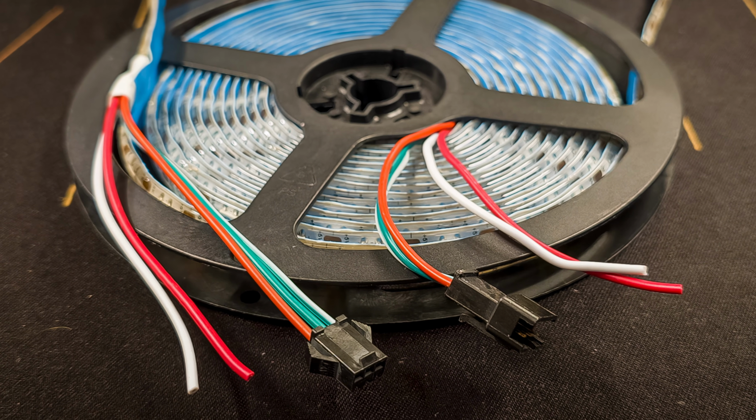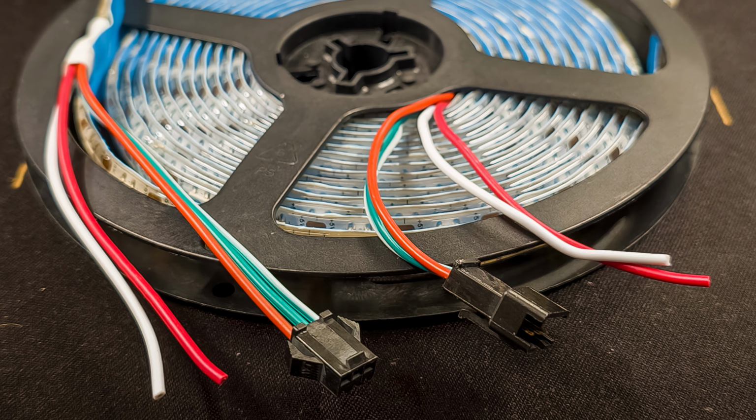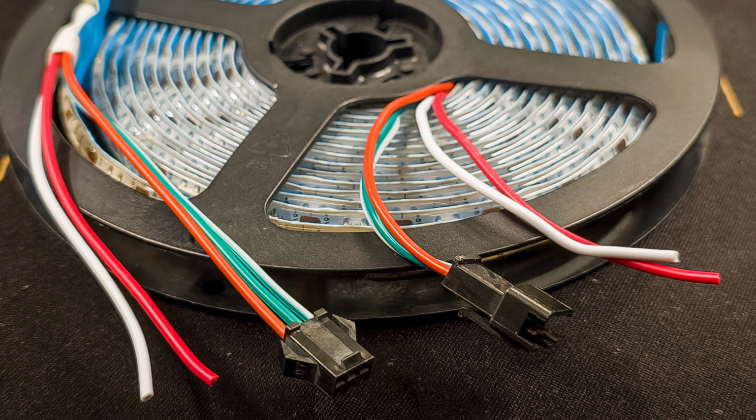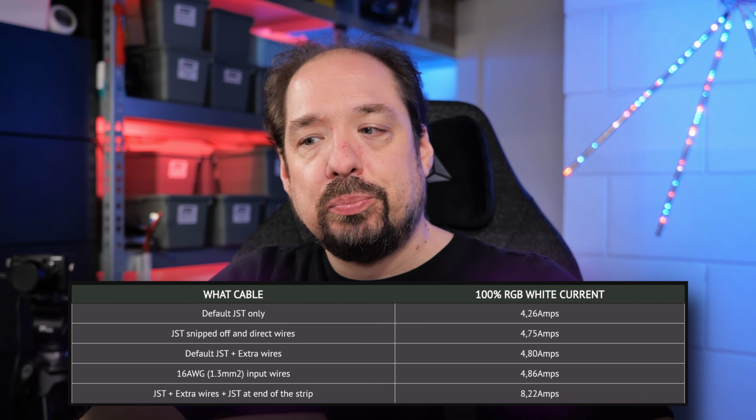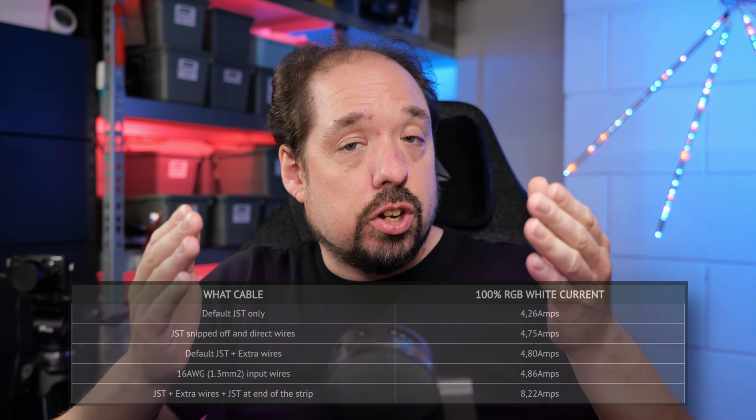Just to make it easier, you can inject at any point, but then you have to solder. And generally these strips come with those little two pigtail wires attached. At the front of this video, we already tested that, and we can use those. We don't need to change those for thicker cables, and we can inject power there.